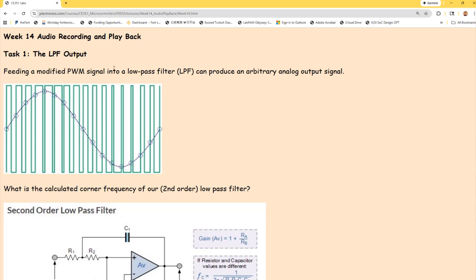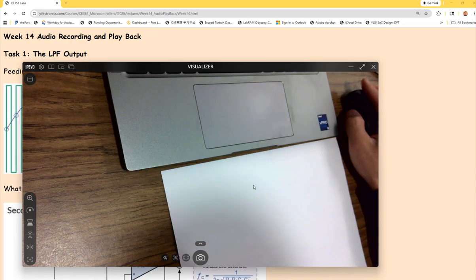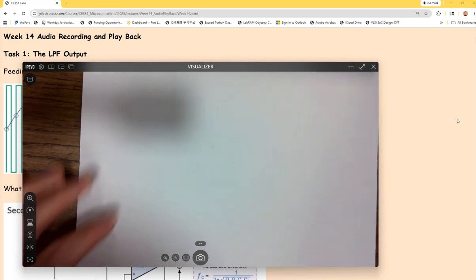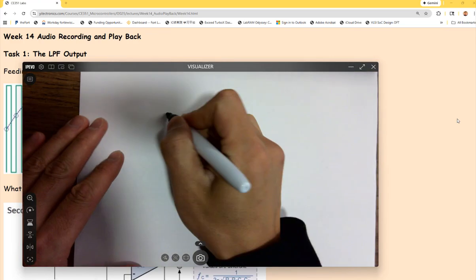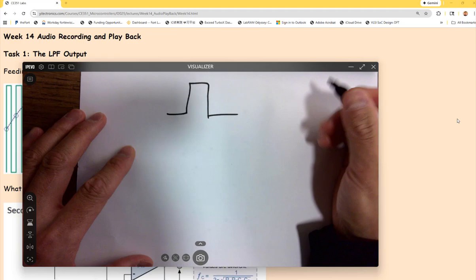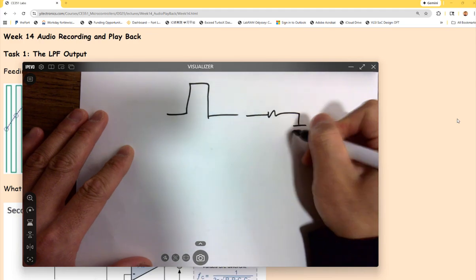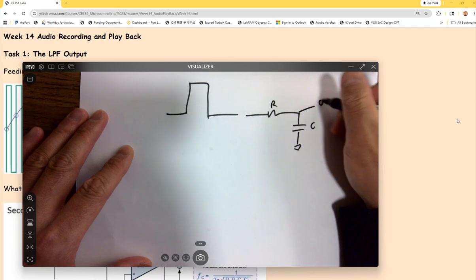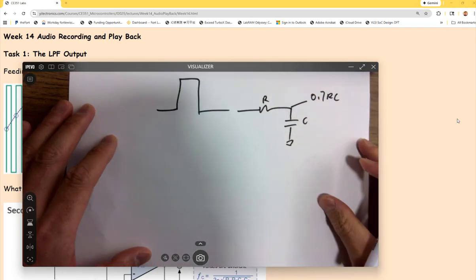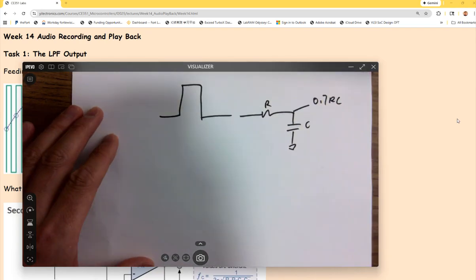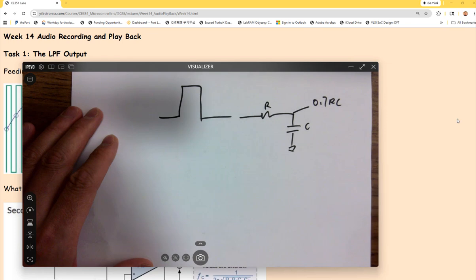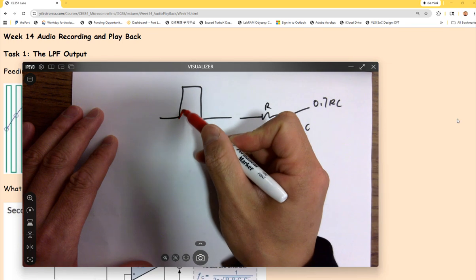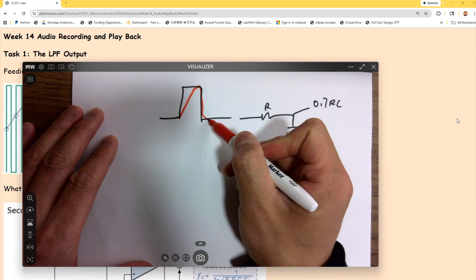It's about physics, okay? Remember we talked about time delay. I mean, in VLSI or in Circuits 1, we have talked about time delay. If you have a digital signal like this going through an RC circuit, what's the time delay of it? 0.7 RC, right? There's a time delay. So the reason for that is it takes a finite amount of time to charge up the cap and then discharge like this.